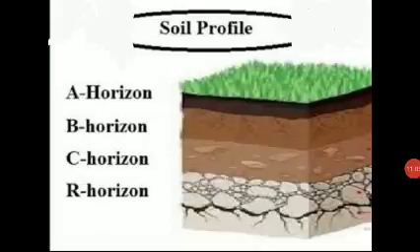The next physical property of soil is structure. It signifies the arrangement of soil particles, sand, silt, clay, organic matter, etc. in the soil mass into porous compounds called aggregates, which are separated by pores and cracks. The soil structure is important to soil productivity, soil permeability, root growth, and soil genesis. The common types of soil structure are granular, prismatic, blocky, and massive.